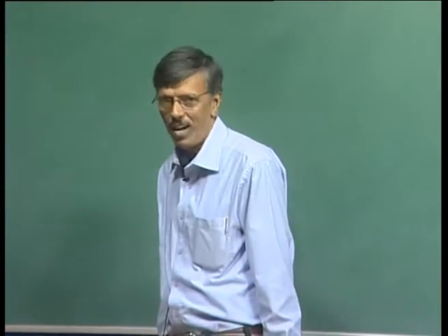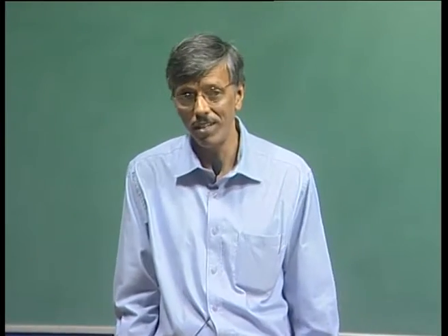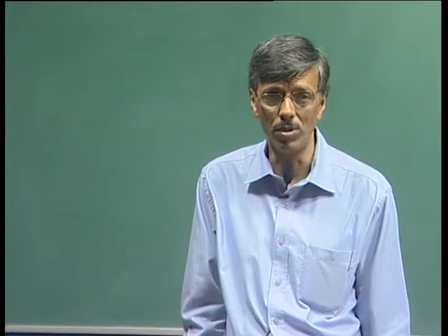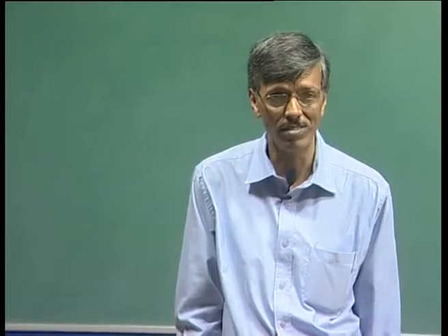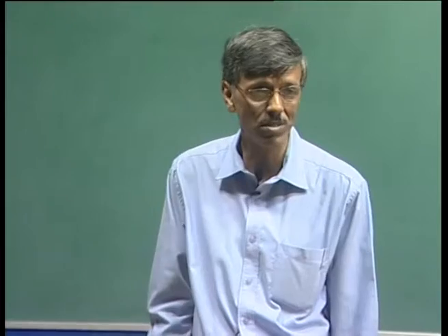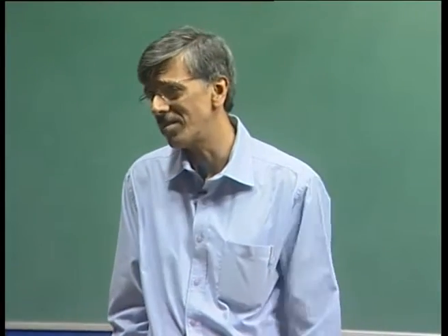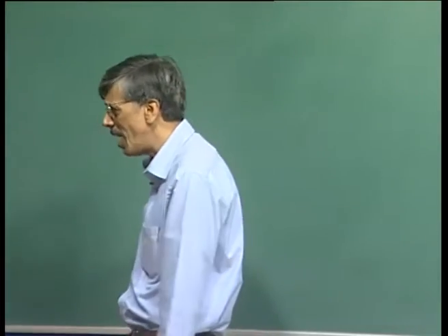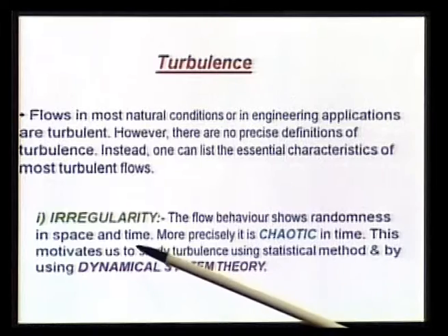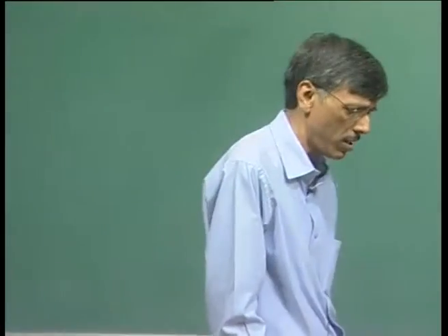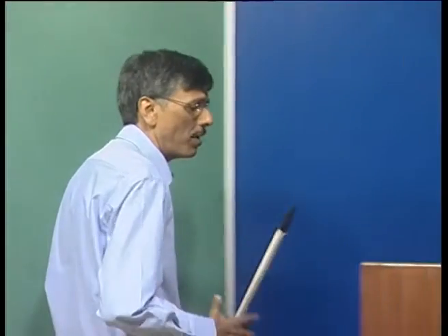deterministic structure. And you are now really ready to appreciate that point of view, because that is what we have done with our POD analysis: we will take a completely stochastic dynamical system and project it onto a deterministic basis. So, those deterministic bases are nothing but your so-called coherent structures of turbulence. Okay. That is why people may like to study turbulence using statistical methods, or they may like to study it in a dynamical system framework like what we have just now done.